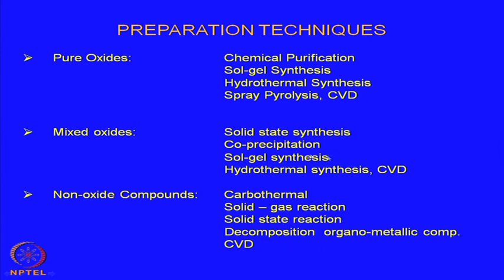Once again, in all these things, because these are non-oxides, oxygen has to be excluded. The presence of oxygen should not be there, and therefore that is an important criterion that whatever you do here, whether it is a solid state reaction, solid gas reaction, carbothermal reaction, or decomposition of organometallic compounds, you have to exclude oxygen. The presence of oxygen must be avoided to make non-oxide compounds, which is quite obvious.